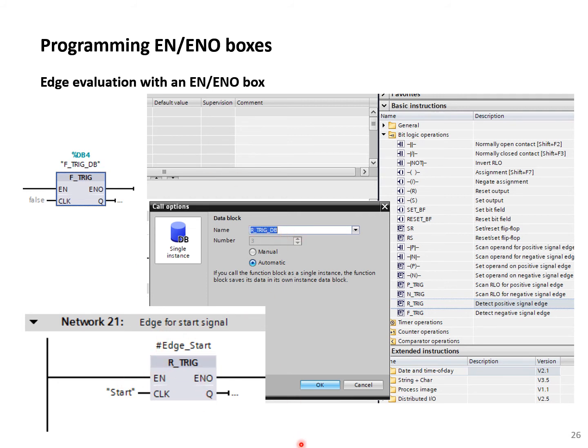You just give it a name, press OK. Now you have a data block in your memory underneath the data block tree, and you could basically use it. So for example, here you have a start button. Once you press the start button, it goes from 0 to 1. This box will be triggered and the Q output will become true.